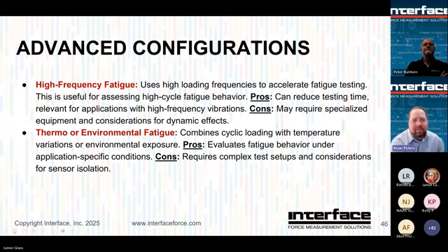High frequency fatigue. So we talked about this. There's the mechanical, natural frequency, resonant frequency considerations you want to take into account. Also, make sure you're up on the DAQ sample rate. High frequency, very high speed testing is a great way to consolidate development time or to shorten it. Just keep in mind, it's obviously going to introduce some other challenges.